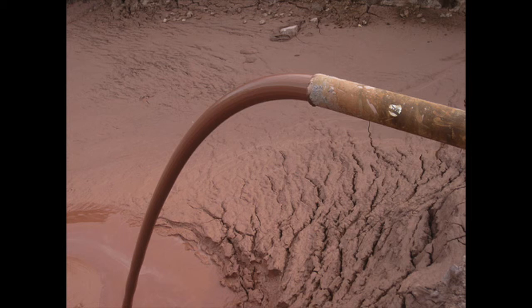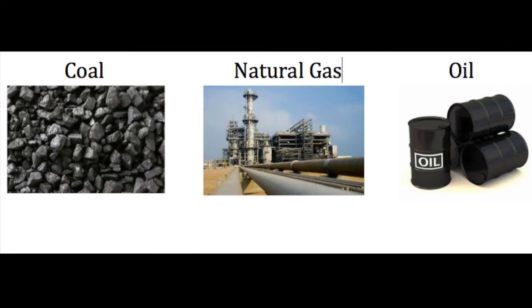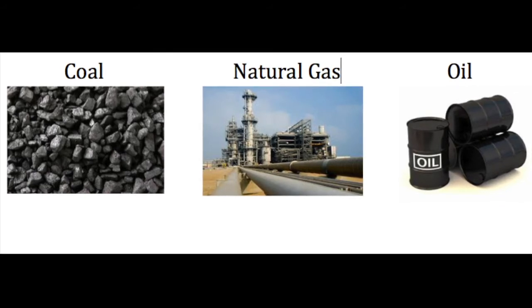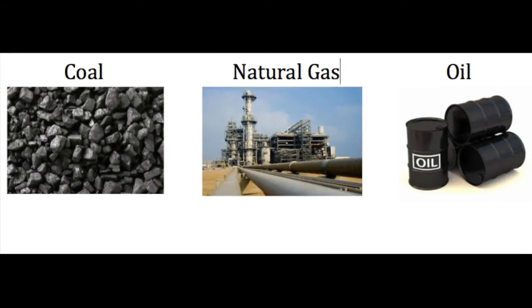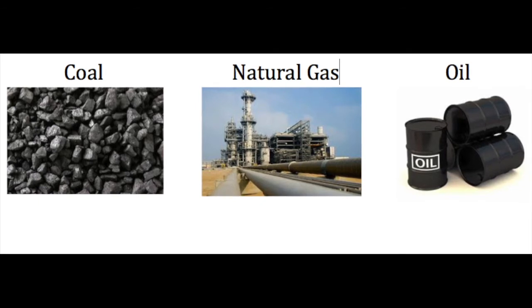Sludge can be recycled back into the process, and this would reduce the amount of catalyst needed while decreasing the amount of dissolved iron in the effluent. A current area of research is the use of sludge as fuel in furnaces and boilers. If this is a viable option, it could reduce the cost of the process and be used as a cheaper alternative to oil, coal, or gas in industry.